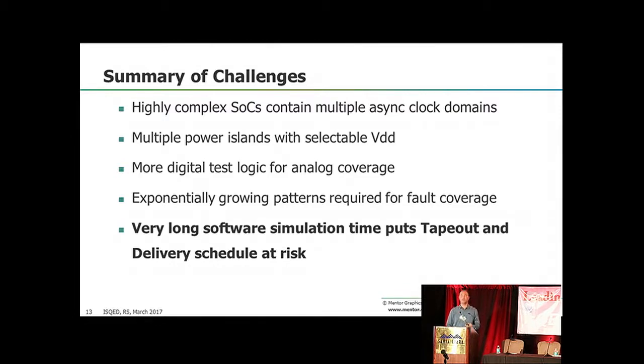All right, so a summary of challenges. This is not exhaustive, but it's a pretty good list. SoCs are getting much more complex, with multiple clock domains and multiple voltage islands, so you have to add more and more test logic to get the part to behave on the tester. That leads to an exponentially growing pattern set, not just the number of patterns, but the different types of patterns required to cover all of those faults. The common challenge with all of these is that it just takes forever to simulate them. It's going to put your schedule at risk.